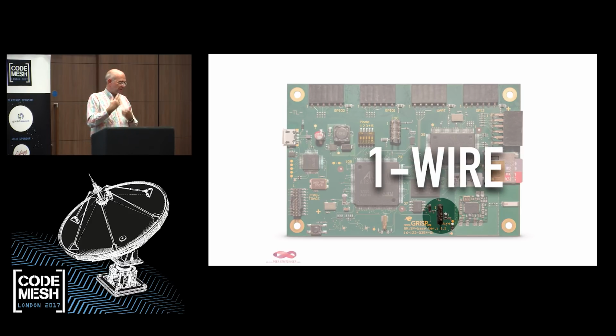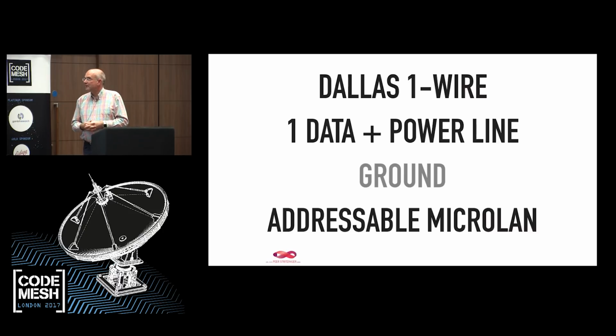And so occasionally you get conflicts on the I2C, and then you have to actually see how to manage the different hardware. Dallas one wire is actually a lie, because it's not one wire, because you always need a ground layer, but it's ground plus one wire. And marketing made one wire out of it, probably. So you have only two wires, and you have your power over these wires and the data.